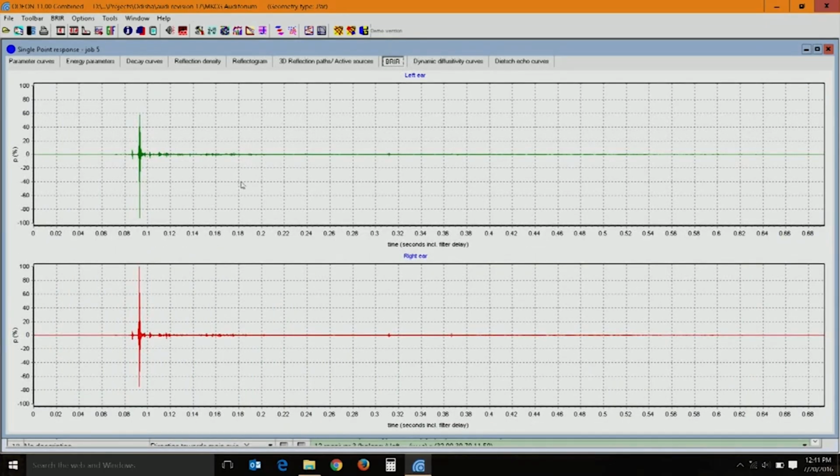Then you have the binaural graph. With two ears, both of them should get the reflected as well as the direct sound more or less at the same time. There should not be much time difference between the sound received in the left ear and the right ear. Keeping this in consideration, the binaural graph really helps. This gives you, with time on the x axis, at what time your left ear and right ear start receiving the signal and how sharp they are.